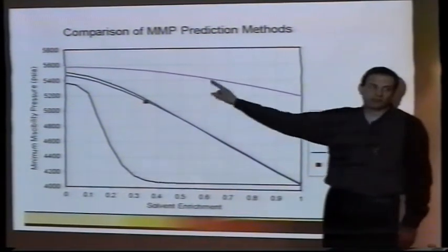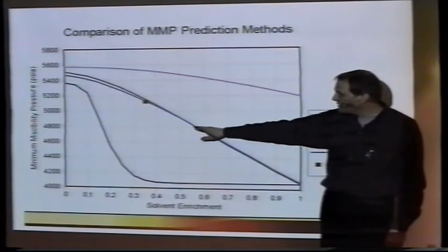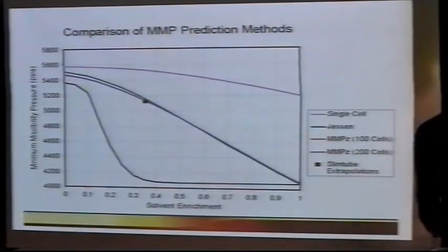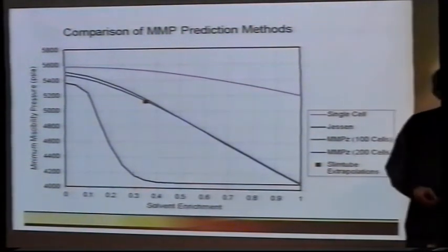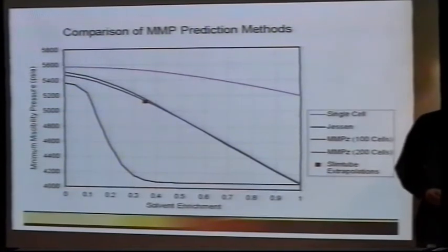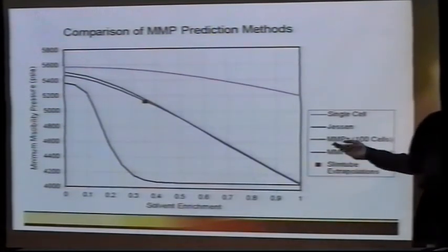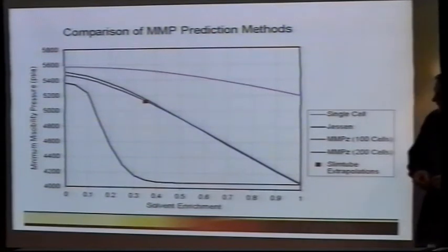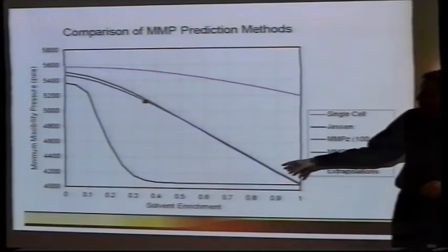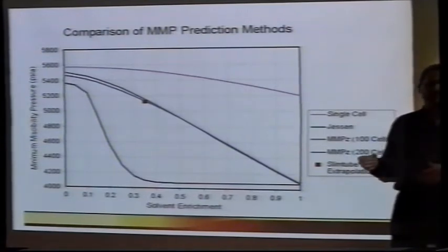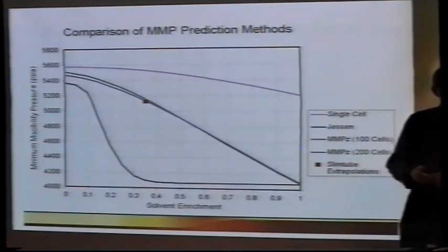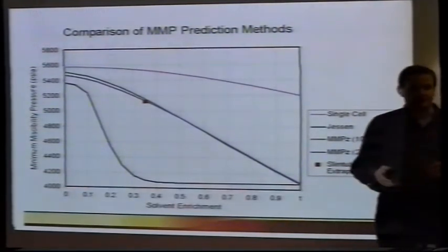These two are two different physical mechanisms. This one is the minimum for miscibility. This one is the minimum for vaporizing gas drive miscibility. This solvent enrichment is based on how many components? Well, it had quite a few. It had everything up to C7 or C8 in it, I think. The fluids are in their paper. I don't have a reference handy with me, but Curtis could always give you the reference to that paper. So they described their fluid systems.